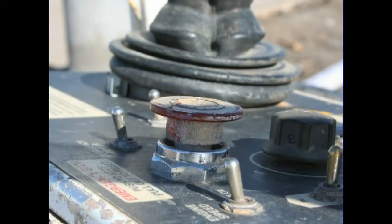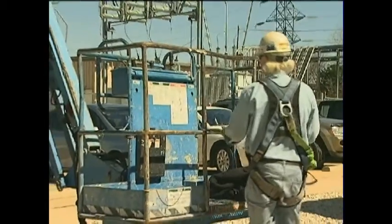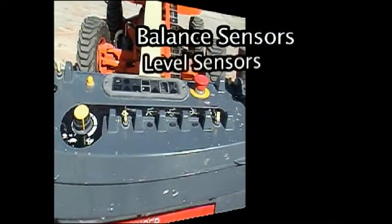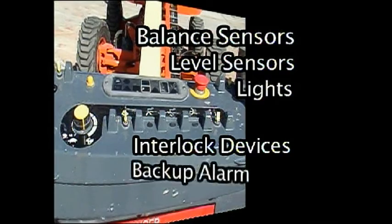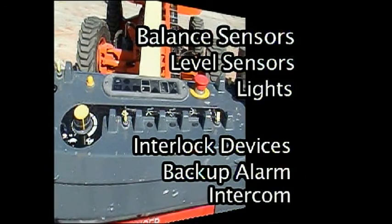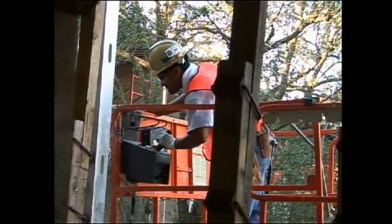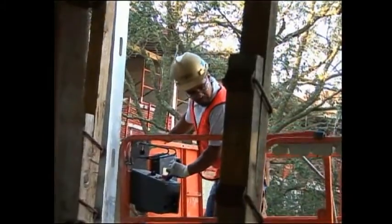Emergency stop buttons should work correctly. Tires must be properly inflated and inspected for damage. All safety guards should be checked for malfunctions. Check balance sensors, level sensors controls, lights, interlock devices, backup alarm, and intercom for proper operation. The emergency descent system should be checked by raising the platform a couple of feet and then turning the lift off and using the auxiliary power to lower the lift.